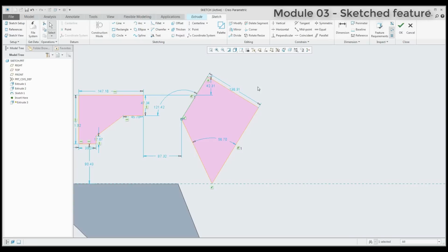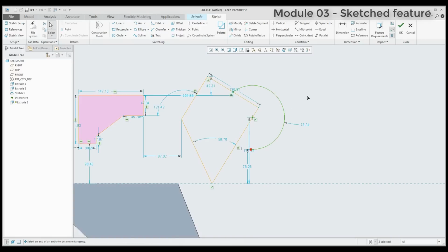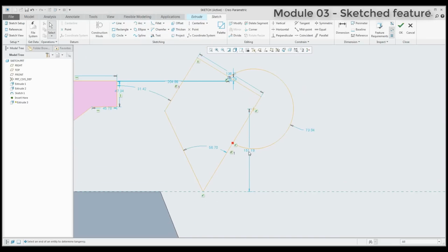And what about an arc? Again, it works the same. You would like to, for example, snap it here, lock, confirm, and select another one and create some arc. And yeah, I will select the end, and with the Control button I will extend it. What is necessary to do? Delete these lines. Again, it's up to you. You can use the Control button.